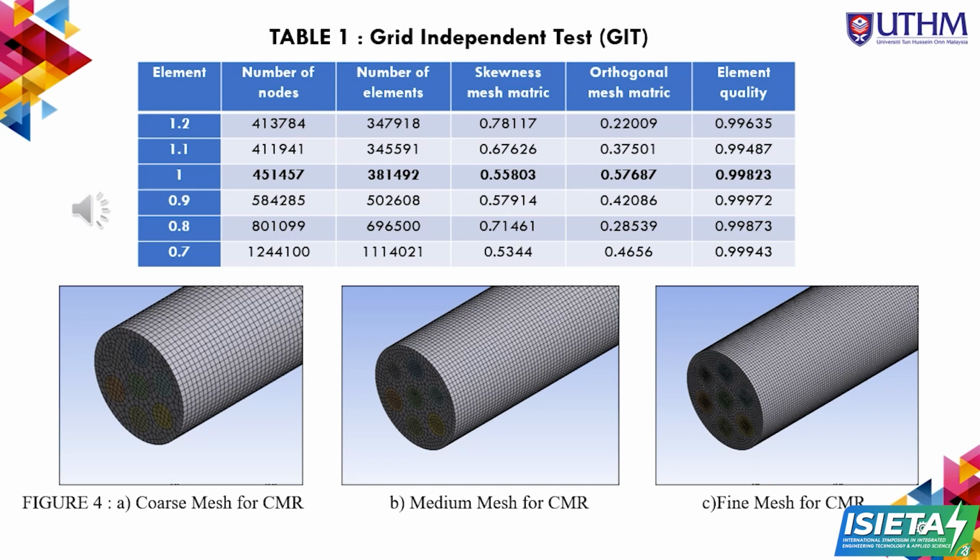Even though employing a coarse mesh speeds up calculations, this approach is still inappropriate for this inquiry. There is no denying that a finer mesh produced outcomes that were better and more palatable. This is because it effectively captures flow information, having the most nodes and elements.